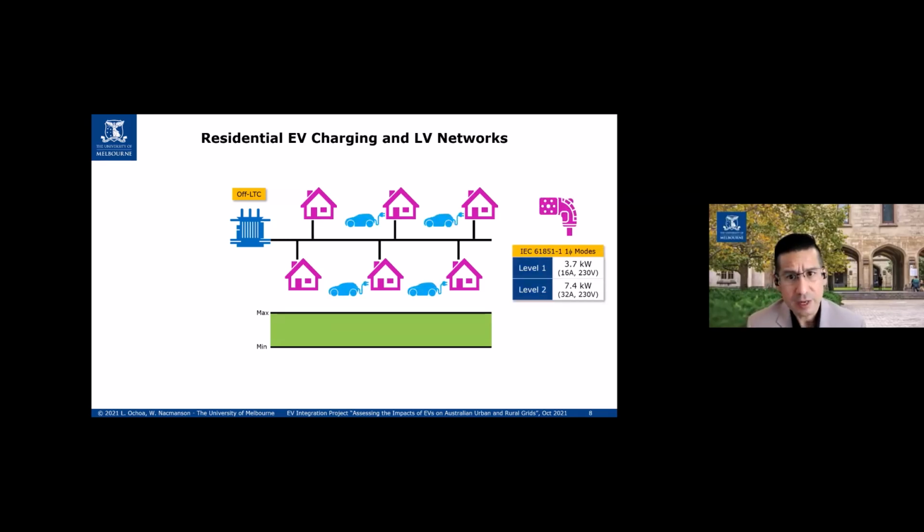Now, let's talk about electric vehicles. The thing is that we have, internationally speaking, different charging types and different standards. The standard that is becoming more common is the IEC 61851, and when we look at the single phase modes, they are called modes in the standard. We call them here level 1 and level 2. These are charging demands of 3.7 kilowatts for level 1 and around 7.4 kilowatts for level 2. Now, most people will not want level 1 chargers because it means less demand, which means a longer period of time to charge your electric vehicle.